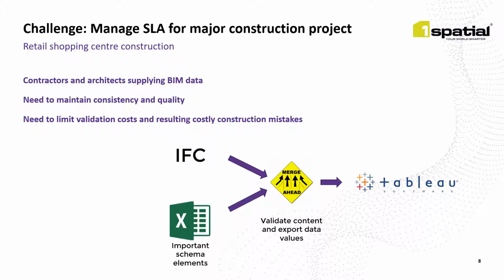To address the challenge of siloed data, we helped by building an FME process that linked all the necessary raw data materials together, with FME directly connecting to material lookup lists and the spreadsheets that contained the allowed building specifications. Then an automated routine was constructed that was built in such a way that it could be used to quality check 100% of the 50 IFC files each week against the client's exacting requirements.